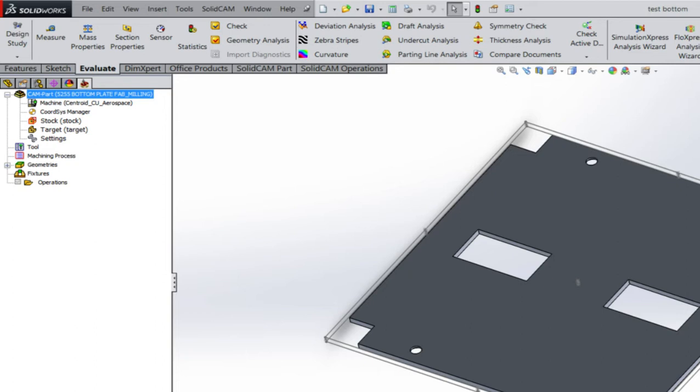Now what we're going to do is talk about two different toolpath operations. The first one we're going to talk about is pocketing. So we've had drilling. That's very important. It's very common to drill holes. Now we're going to talk about pocketing. And what pocketing means is taking a closed boundary and chewing out everything inside that boundary.